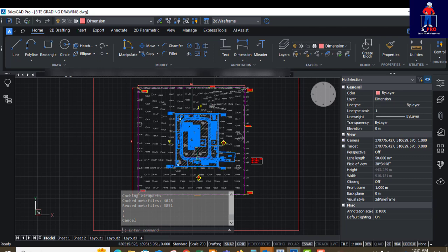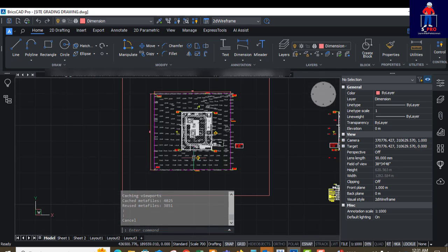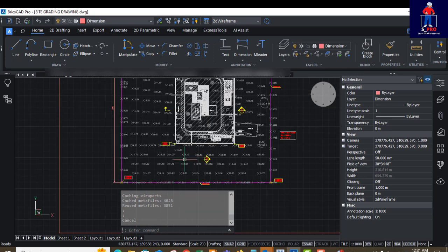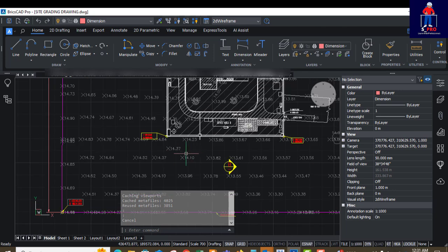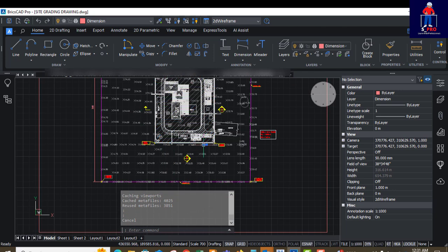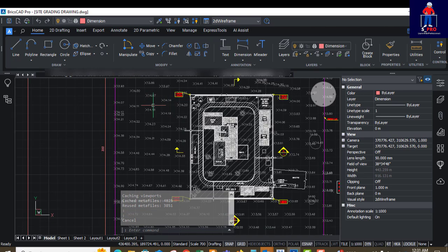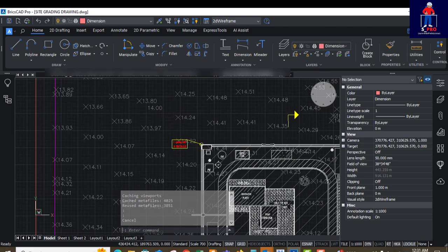But in this particular design, when I went to the site visit, I was able to communicate with the client. The client walked me around, and I asked the client a lot of questions. So he told me that the place is prone to flooding. Each time there is a heavy rain, the whole place used to be flooded. So that suggests to me that I need to raise the site up. Okay, so if you observe this spot height, you will know the level.